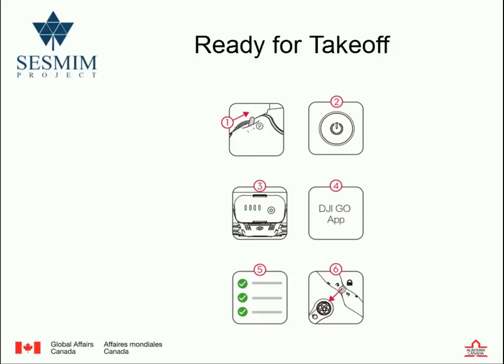You have two ways of starting and stopping the engines. One way is to use the up arrow button here on the DJI app, then slide it over. The other way is when you pull the two buttons into the middle at the same time, it'll start the engines. When you pull both down to the middle, it'll also stop the engine. Okay, so now we can just power down, in the reverse sequence of what you started with.